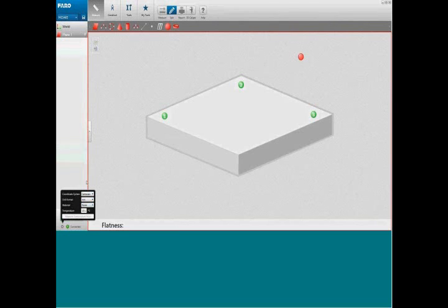And where there's a need to compensate for temperature for the material and for the component, the user can also select the material from here and can also manually enter the temperature of the material from here. Where a Faro temperature probe is attached, the temperature will be calculated automatically every 5 minutes and used within this window. The temperature window here will become read-only.